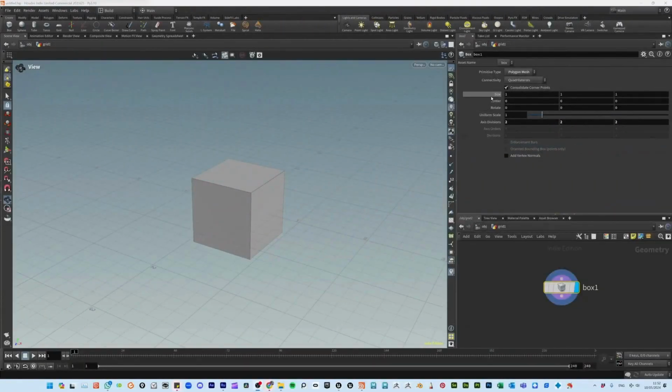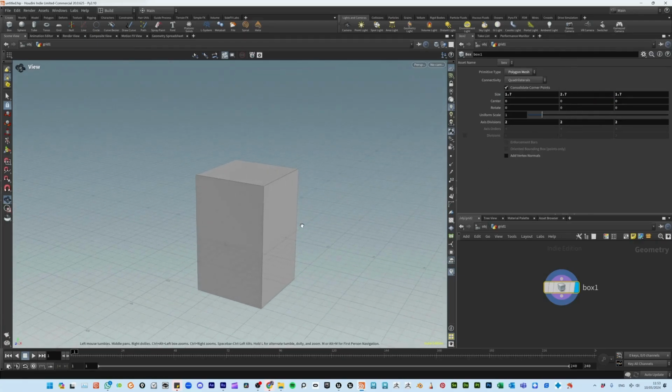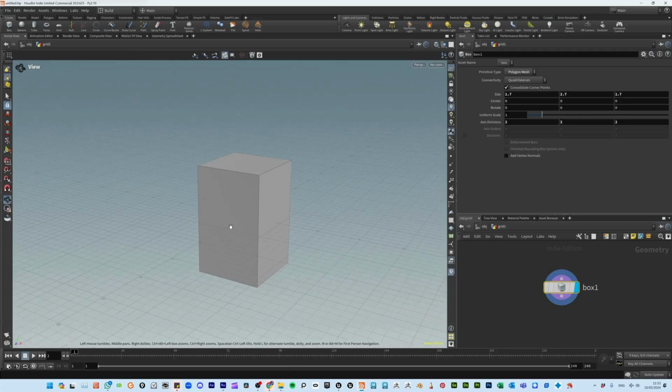In Houdini, I can take each parameter I'm using and reference it and use it with other parameters. Let's see an example of it. Here, I take a cube and I can play with the size and with the height. And a nice trick, if I want this cube to always be on the floor, I can take this number, divide it by half because this is the middle point, and have the center start from there. So let's say this is 3 units. I would like the center to be at 1.5. Then it's always on the floor.